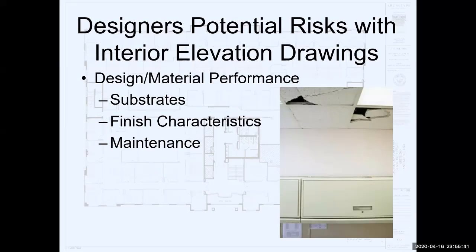So another element that is associated with these risks is, as we've talked about in the past, how does our design work with the existing condition, especially as relates to substrates? Is the material that we are applying to the existing wall or even the new wall appropriate for the type of finish we're putting on there?